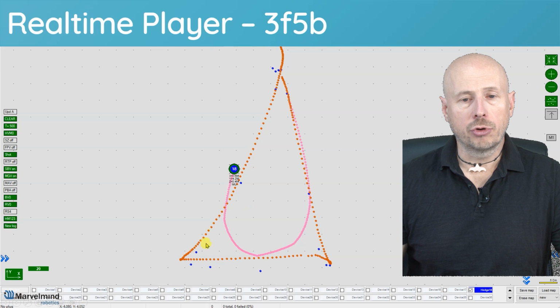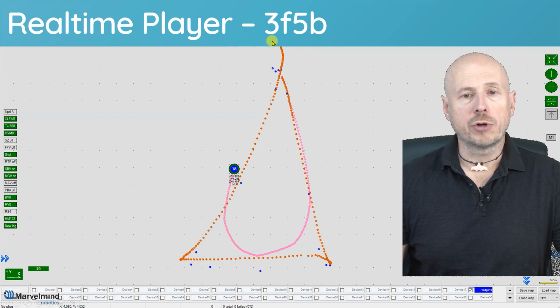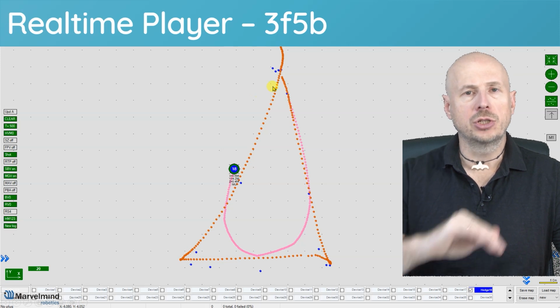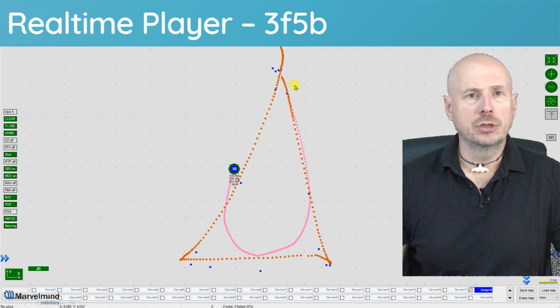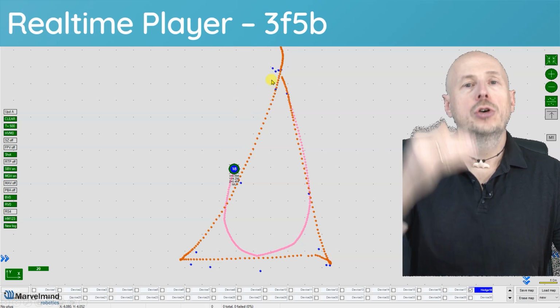So just another example for another sharp curve. You see it's making an even smoother curve, but cutting the corners even more. And you see, since it's expecting 3 forward points, but they are not available, it means that it's another drawback of this. Typically, it's a minor drawback because I have a much longer track, so it's typically not a problem. But nevertheless, pay attention that you will not be able to achieve the end of tracking unless you have sufficient points forward.